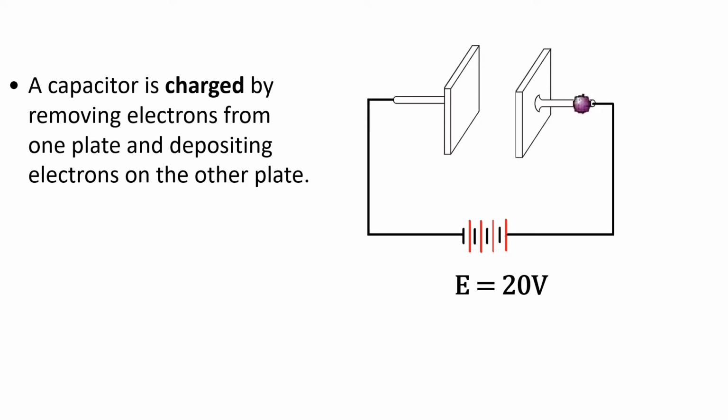So an electron will come off of the metal plate of the capacitor. That forces the one plate to become slightly positively charged. Since there's a difference of charge on our capacitor, where one plate is now slightly positively charged compared to the other, the second plate will then pull an electron out of the pile of electrons on our battery and place it on its plate in order to balance out the system.